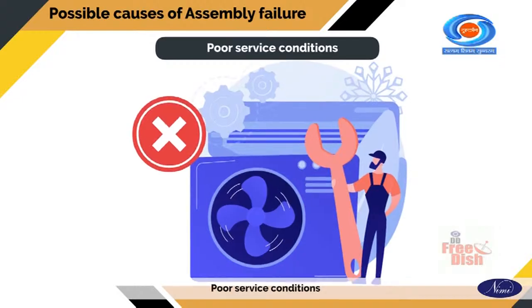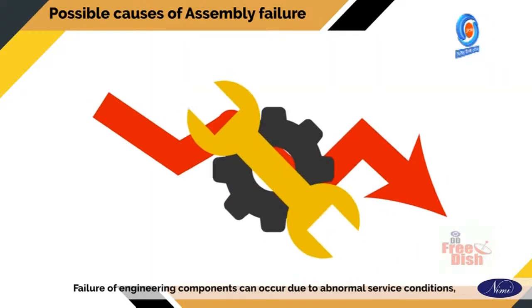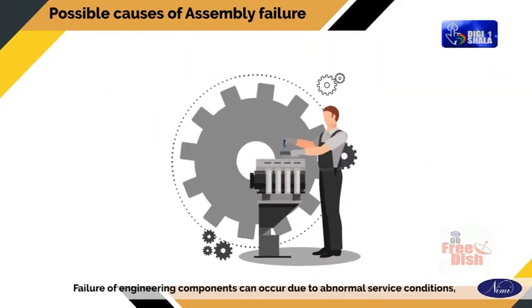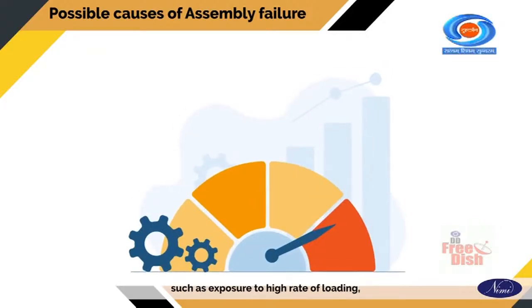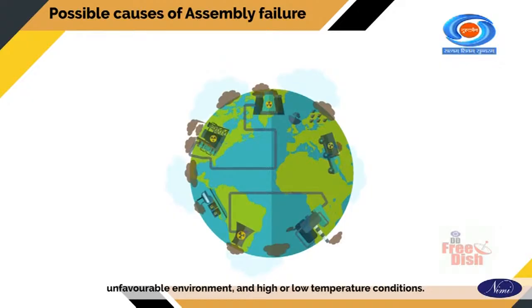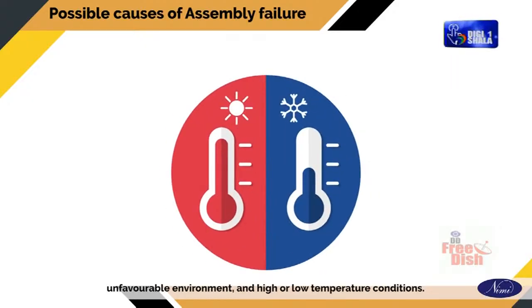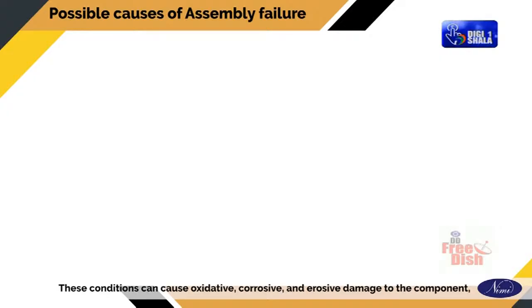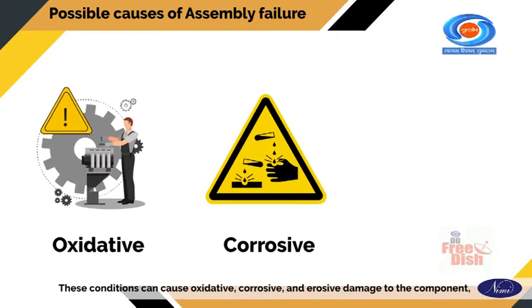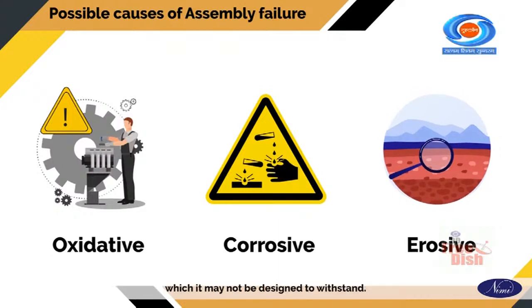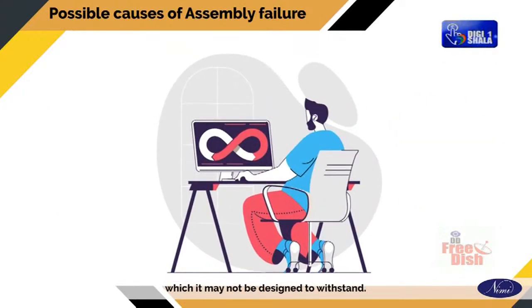Poor service conditions. Failure of engineering components can occur due to abnormal service conditions such as exposure to high rate of loading, unfavorable environment, and high or low temperature conditions. These conditions can cause oxidative, corrosive, and erosive damage to the component, which it may not be designed to withstand.